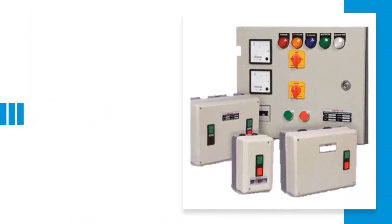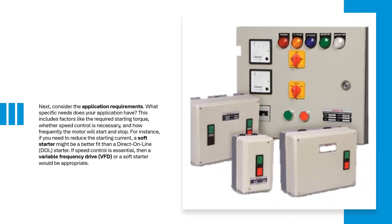Next, consider the application requirements. What specific needs does your application have? This includes factors like the required starting torque, whether speed control is necessary, and how frequently the motor will start and stop. For instance, if you need to reduce the starting current, a soft starter might be a better fit than a direct online (DOL) starter. If speed control is essential, then a variable frequency drive (VFD) or a soft starter would be appropriate.